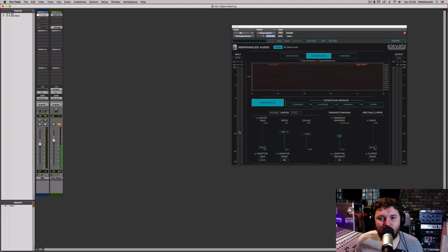So why would you want to look at a peak meter versus an RMS meter? Well, you would look at the peak meter to make sure you're not unintentionally clipping your audio and that you're not distorting it. But our ears aren't necessarily hearing those fast fluctuations. So an RMS average measurement is closer to actually how we're hearing the audio. However, it's not a perfect system. So to look at some of its shortfalls, let's go back to our slideshow.